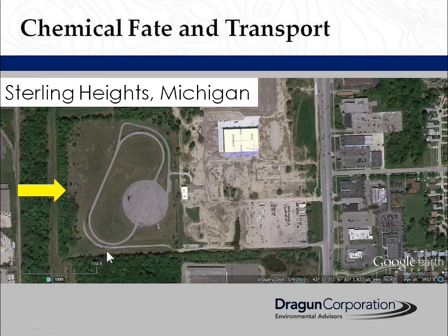The whole problem here in terms of the understanding of the site was the geology was about 4 or 5 feet of sand with a little bit of water, groundwater in it, over like 80 feet of clay. And every one of the wells that they had put in at this site were screened too deep and never indicated where the oil was.